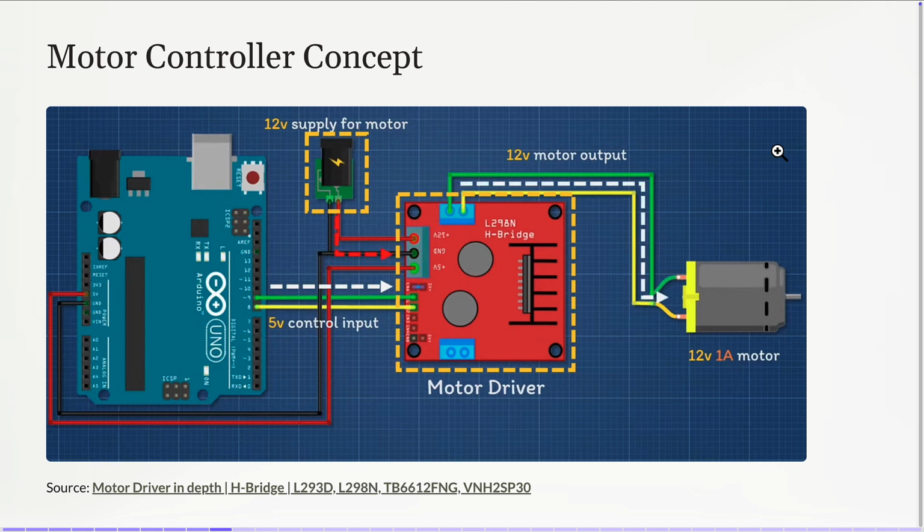And if you remember, this is the same solution that we have in this robotic platform. You can see an Arduino. You can see the H bridge, which is the motor driver. And here we have one motor. But here, how many motors do we have? 2. We have 2. OK. So this H bridge allows you to control 2 motors. It's a dual H bridge, which is basically the same as we have here in the picture.